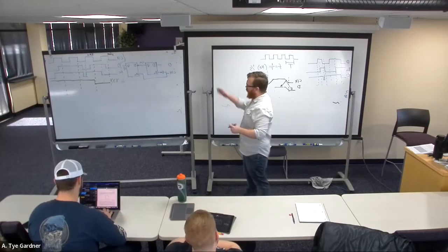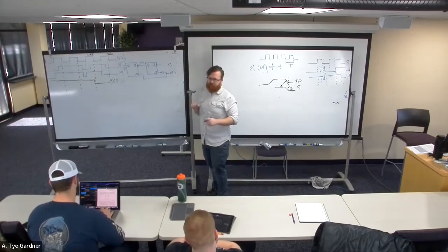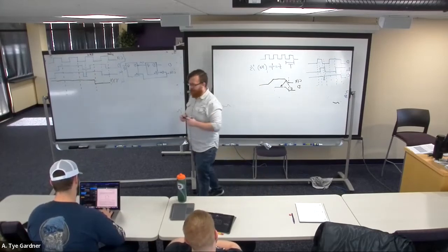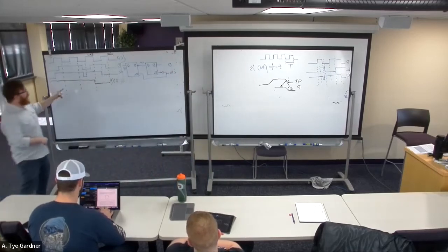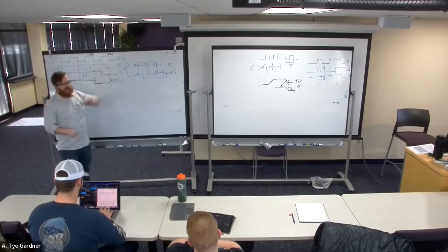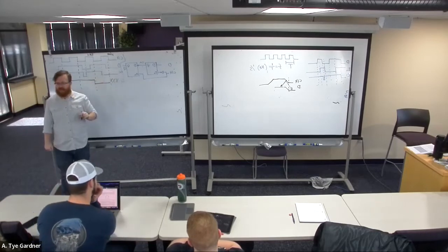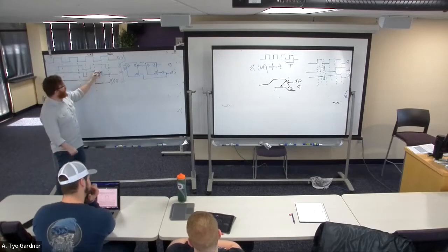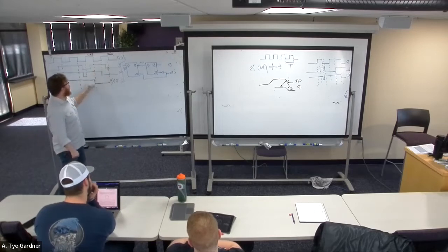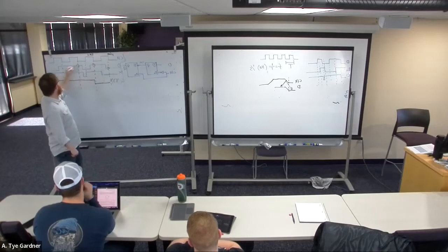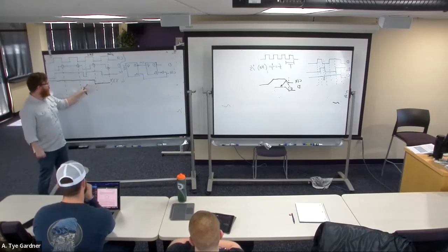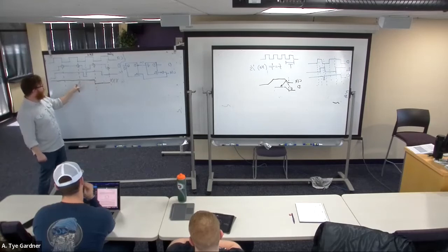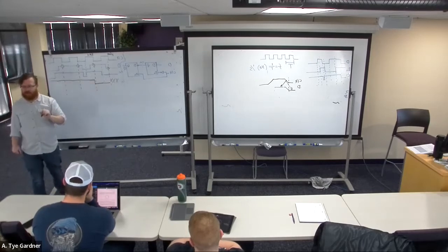So this device is called a D flip-flop. And what's cool about it is I've drawn the timing, but I haven't pointed out the nifty part, which is it only cares about the value of D when the rising edge happens. So if you look at this, it should be 0, 1, 1, 1. 0 transitions to 1, 1, 1.